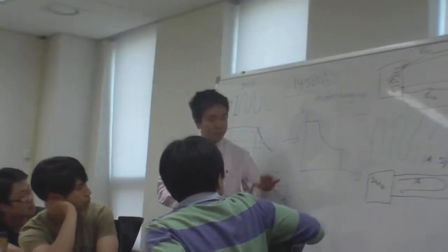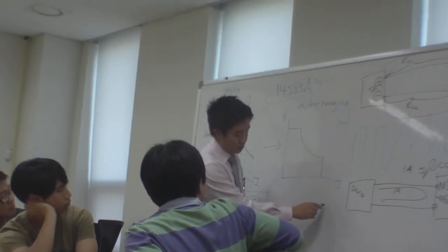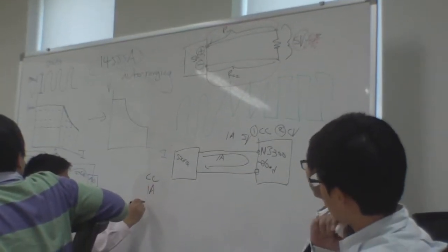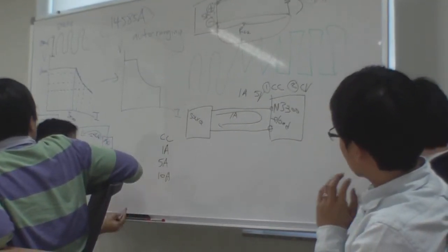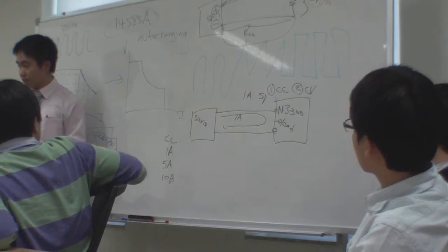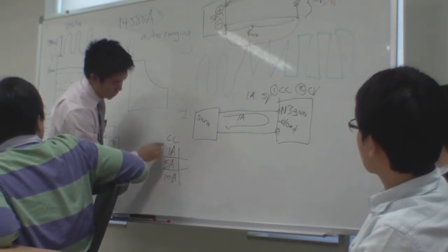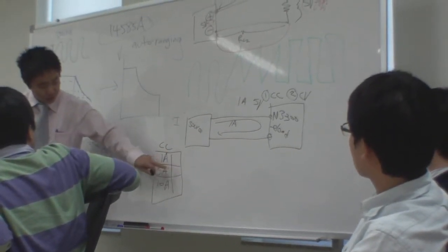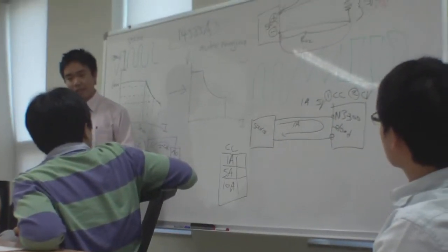And for example, another feature. Let's say you want to do constant current, and you want to do something different. Like you want to pull 1 amp, then 5 amps, then 10 amps. You can actually make a table on the electronic load, and you can put the time that you want it to sink 1 amp, the time you want to sink 5 amps, the time you want to sink 10 amps.